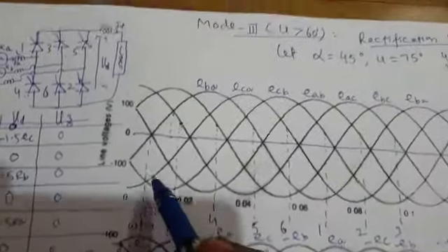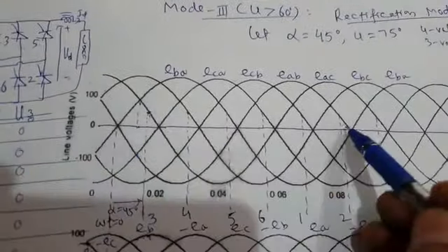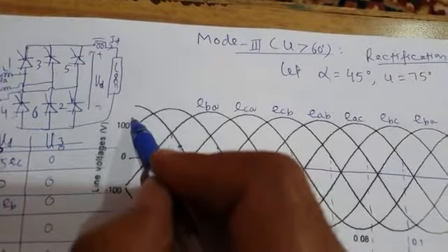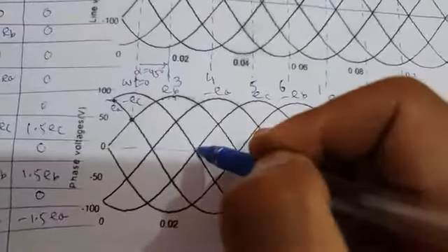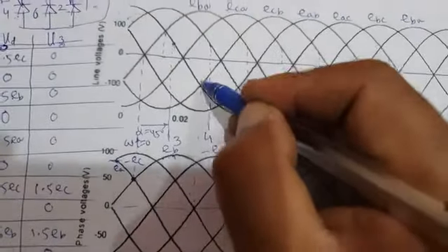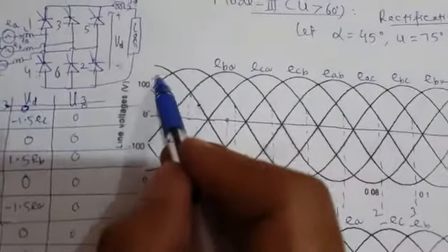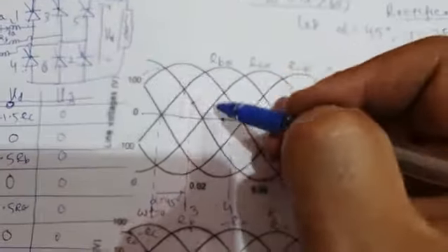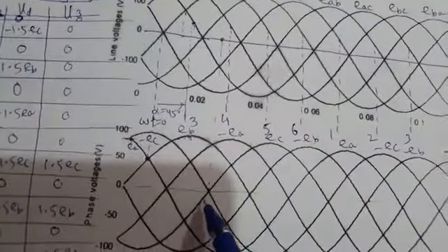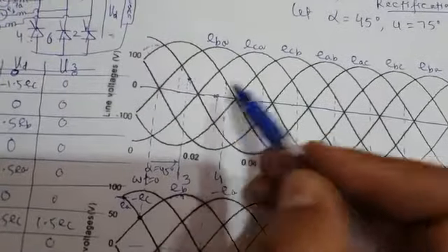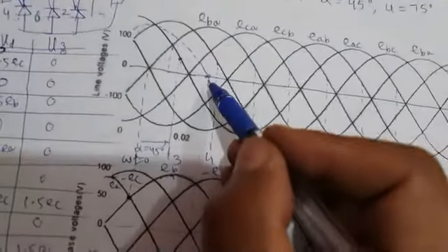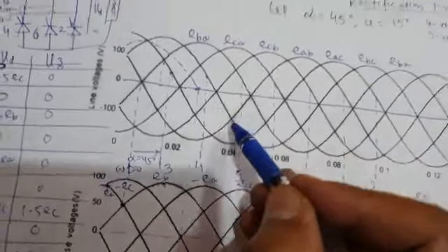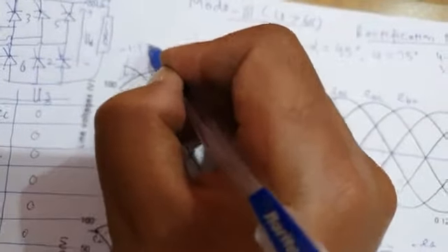Okay. Now we already know if you multiply this minus EC by 1.5, you get minus 1.5 EC, and if you draw minus 1.5 EC on the same omega t axis, it will pass through this. You see, this is minus 1.5 EC. It's 0 crossing here. This is its 0 crossing. So you can come down and get it down to its 0 crossing. So this will have positive half cycle, and then you can draw the negative half cycle, but you don't need to draw the entire negative half cycle. So this is your minus 1.5 EC.